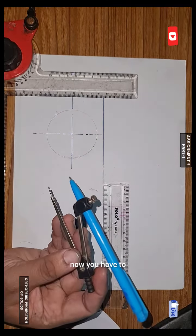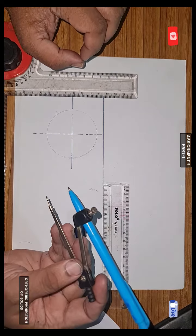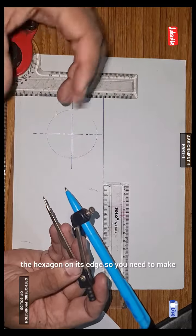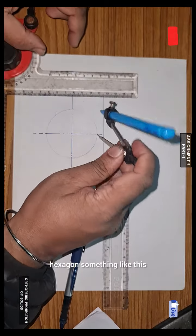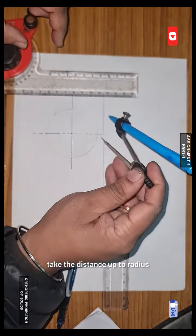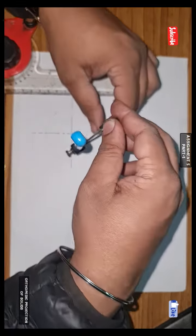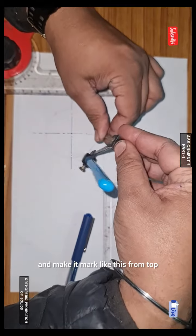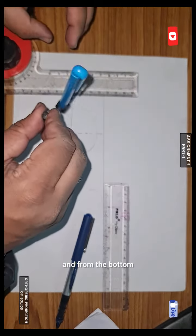Now you have to place the hexagon on its edge, so you need to make a hexagon something like this. Take the distance up to radius and put the compass over here at this position and make a mark like this from top and from the bottom.